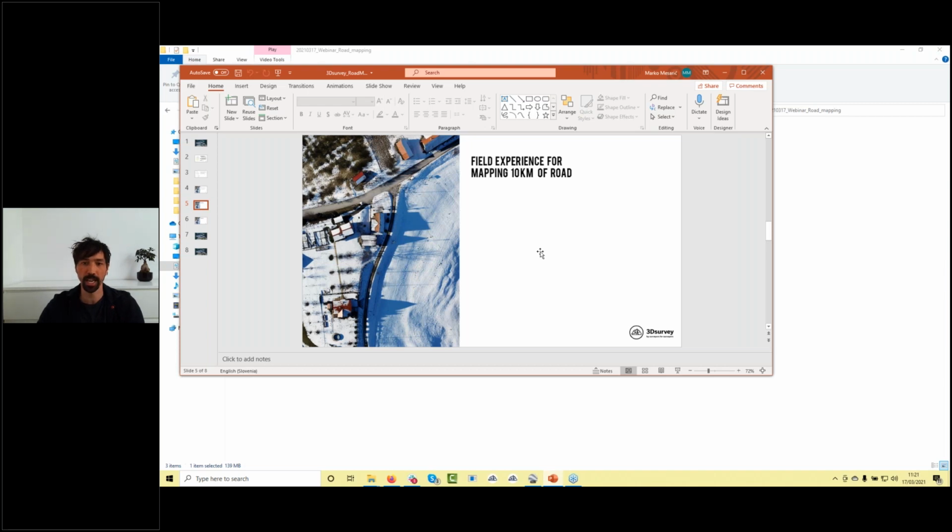This can happen really quickly because when you calculate the overlap between the images, you are calculating on ground level. And if you have high trees, like a forest with 30 or 40 meter high trees, then up on the trees you don't have 80% overlap, you have just 60 or something like that. And this is already critical, okay? Some of the drones, also RTK, Phantom 4 RTK, can follow the terrain. We never tried because at the beginning they had some issues. Not sure if it's better now, but we are still flying those projects at the same flying height, and then you need to keep this in mind, start from the highest point.